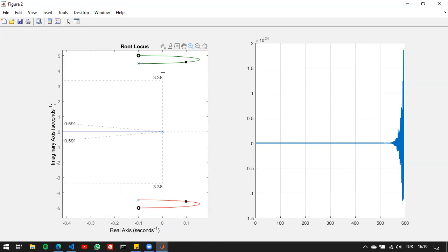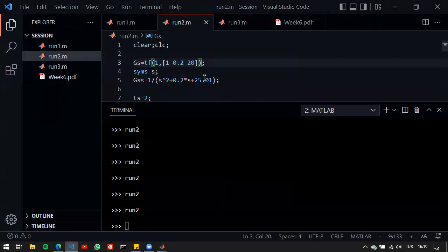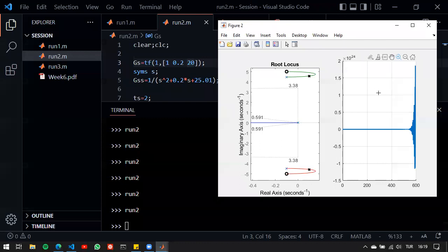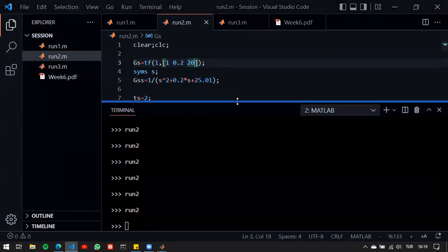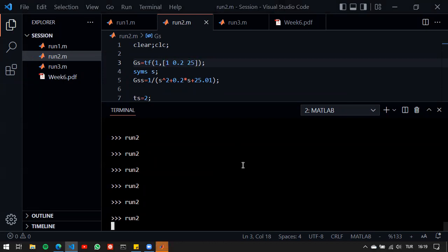So therefore, you should be careful with pole zero cancellation, or you should have the exact position of your poles and not that big of an error in your model, so that you can tolerate this error here. You can see we already have a not stable closed loop, so unstable closed loop. So therefore, it's not really that robust to really cancel poles and zeros here.